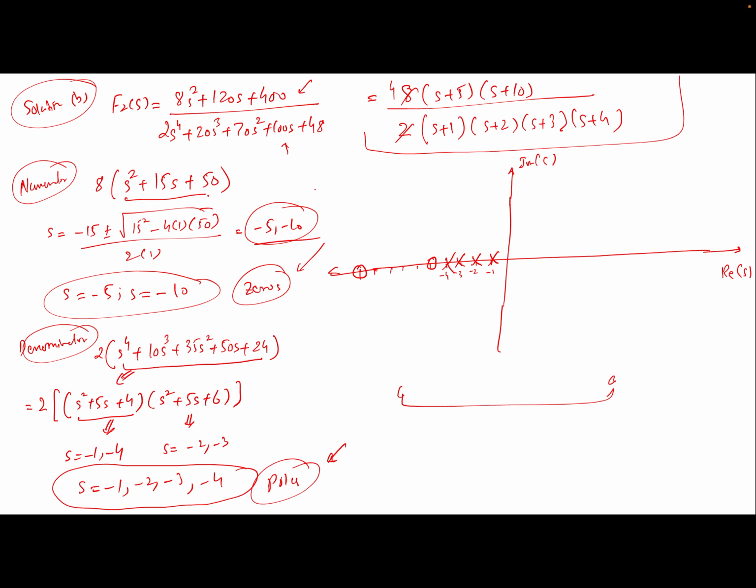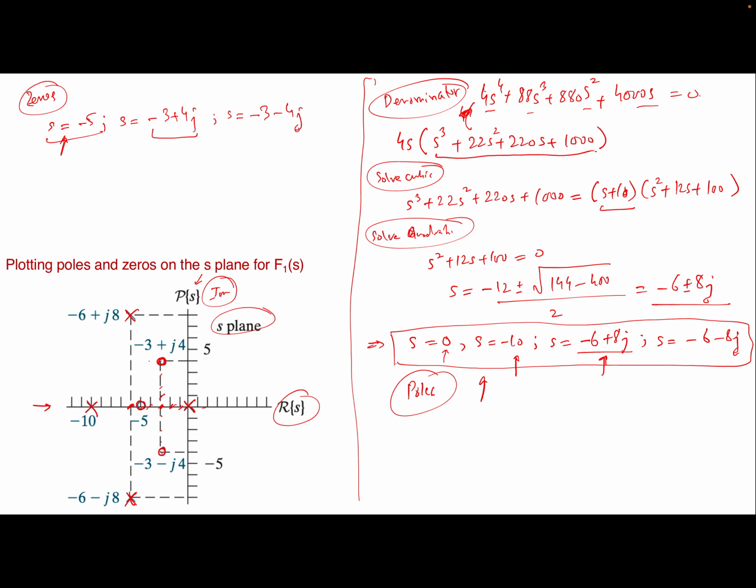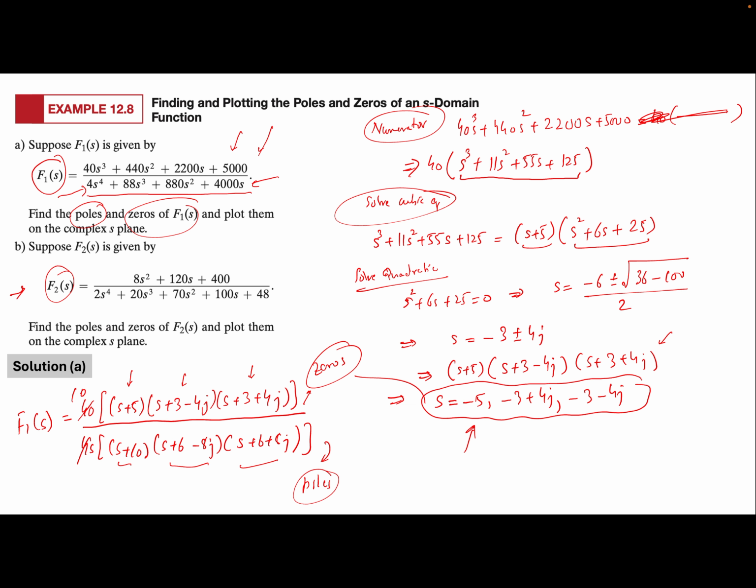Poles and zeros. Essentially, just imagine that this f of s is coming from the circuit analysis where you have RC, RL, or RLC circuits and differential integral equations. You end up converting them into the Laplace transform to get these kinds of equations, f of s. So before we convert it back with the inverse transform to get a time domain function, these Laplace transformed versions can represent interesting things, where in the numerator we have the zeros and in the denominator the roots that make it zero are called the poles, right?